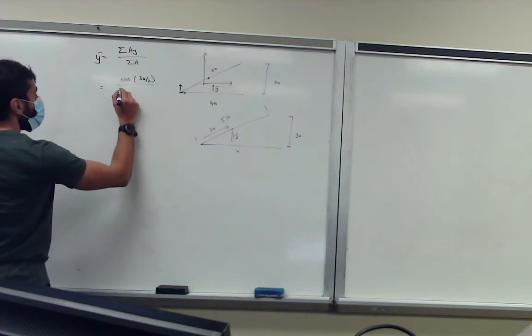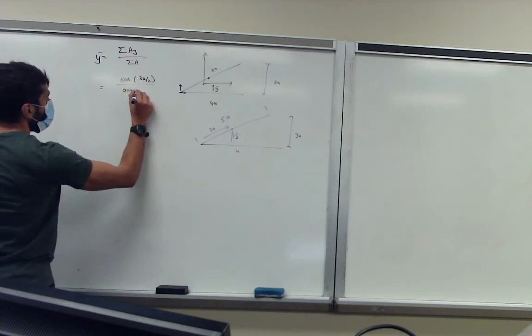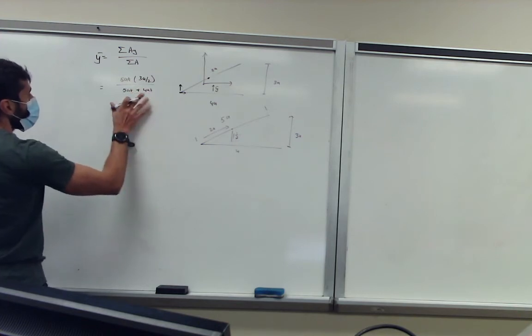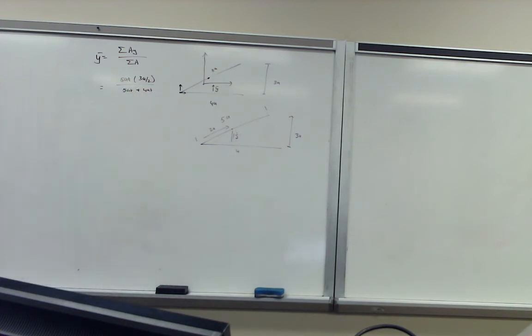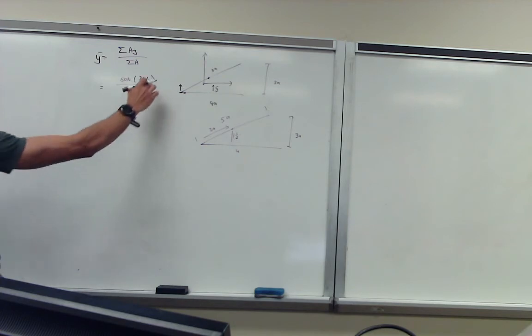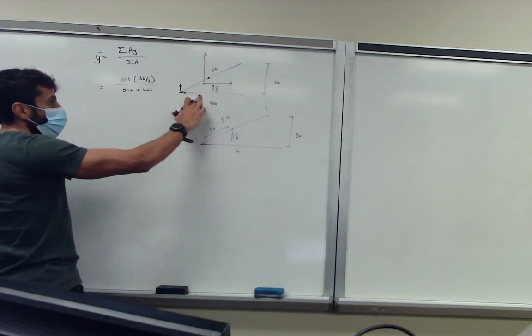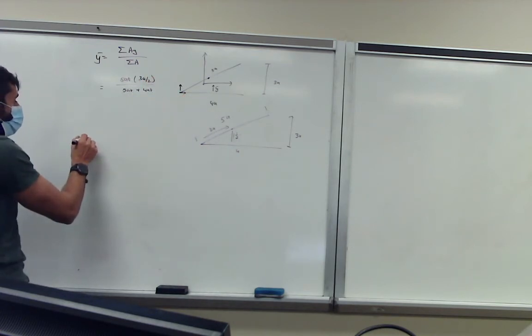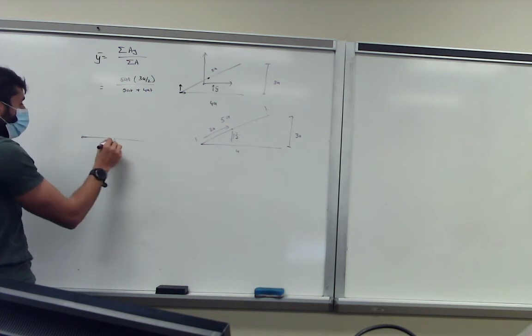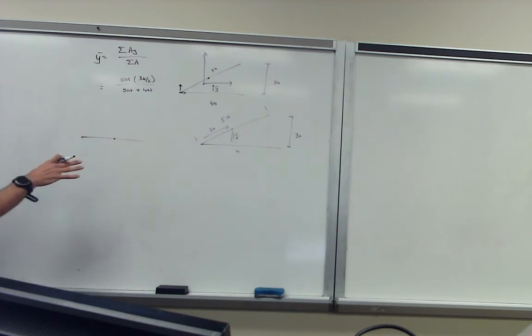Yeah, so this is 5at plus 4at because this is the total area of the full geometry. And we did not have any contribution of this one because we assumed it's thin wall. So you can assume that your reference location and your central axis coincide with each other. So that distance y is t/2, but t is extremely small, so it's 0.